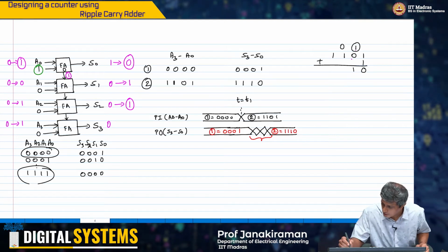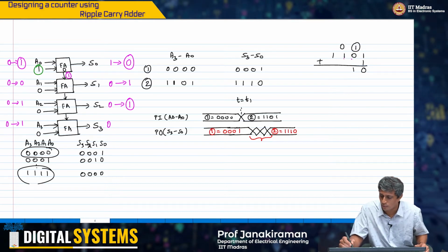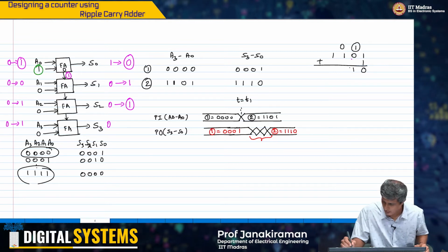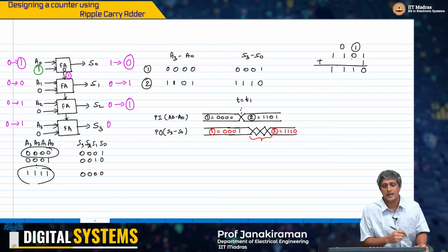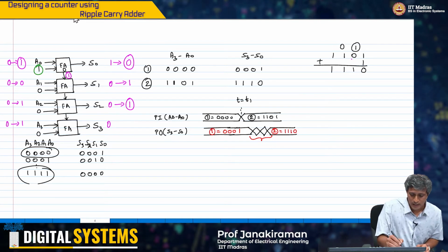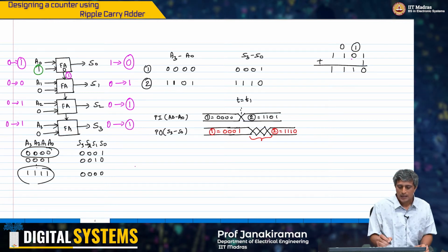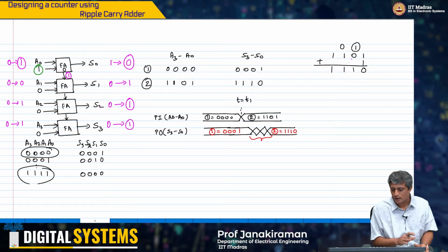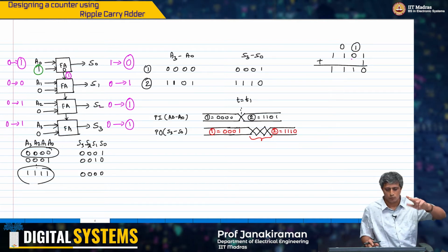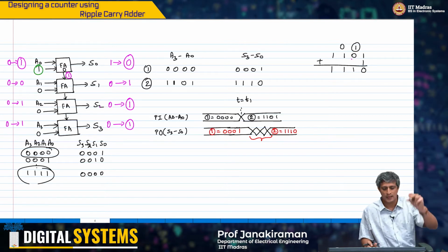And of course now what is happening? I have 1 plus 0 and then I have 0 plus 1, I get the answer as 1 and then 1 as the answer. So what would have happened in this case is this S0, S2, S3 going from 0 to 1, or toggling its state, would have happened after one full adder delay itself.